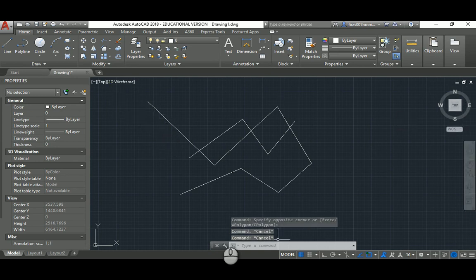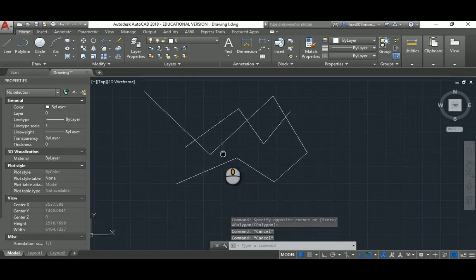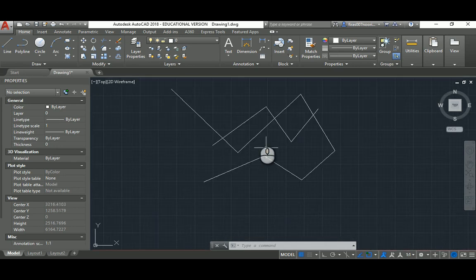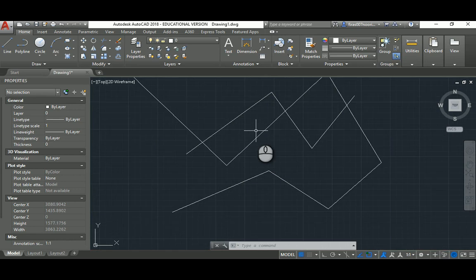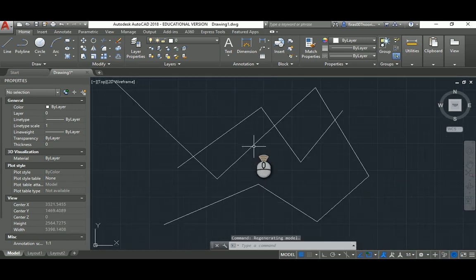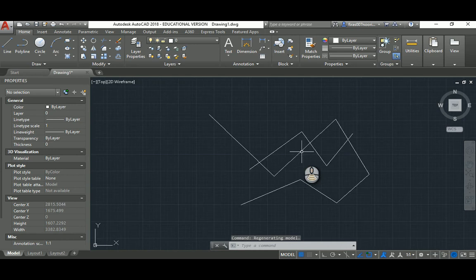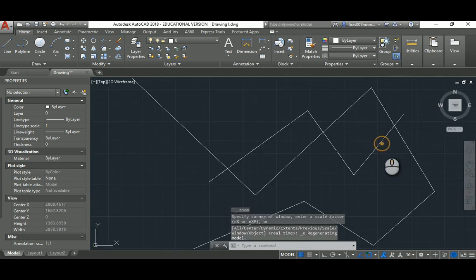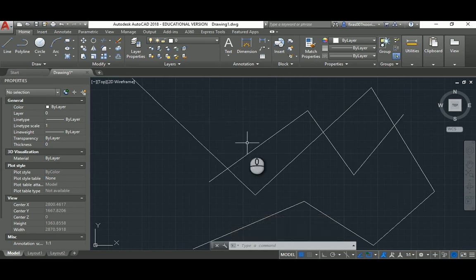Here, that's the viewport, or where you work, and you can click the middle mouse button to navigate or pan. You can zoom in by pushing the scroll upward, and you zoom out by pushing it downward. And that's really an important thing to master. If you double click, it's going to make zoom extents for you. That will make everything in the drawing as big as the size of the screen.